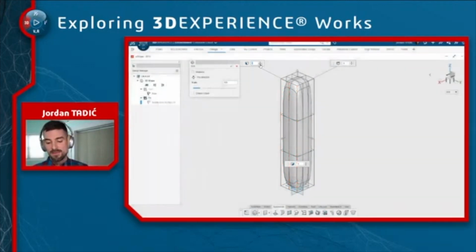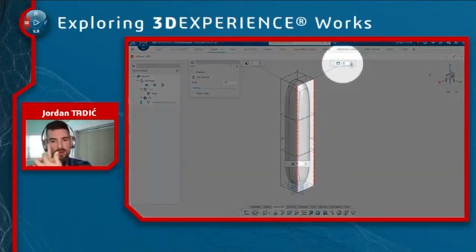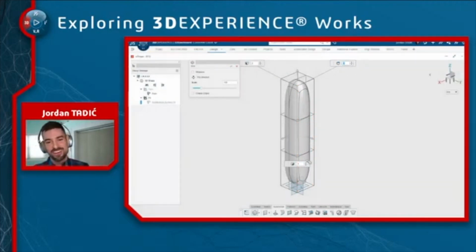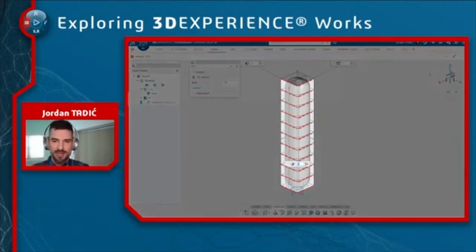Now for the side of the finger, I don't need it to be symmetric from front to back, because we're going to have the knuckle on one side and the little crease on the front. So I'm just going to choose 1 column of faces, which gives me a nice round radius on the side. And then for the length of the finger, I'm going to choose 10. You don't have to get this right on the first try, because you can always insert loops after the fact, or delete loops if you've added too many.